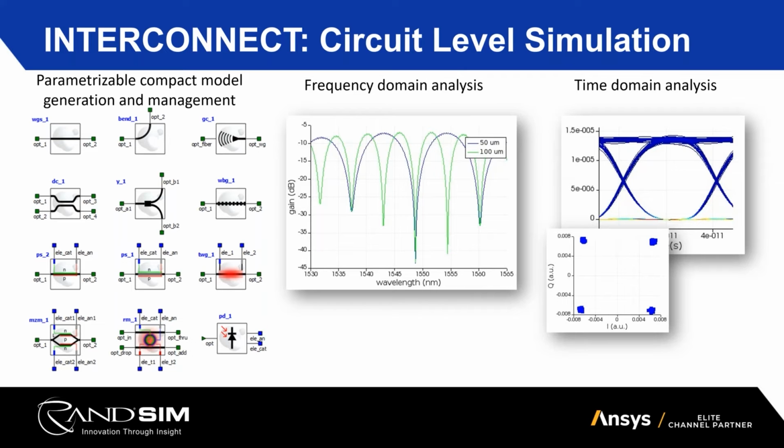For the time domain simulation, INTERCONNECT uses a dynamic data flow scheduler. Basically, this allows for more flexibility than traditional discrete time or time-driven simulators. The scheduler simulates the time domain waveform signals for each element and propagates them bidirectionally. The analysis tool makes it easy to extract eye diagrams and figures of merit, such as the bit error rate.